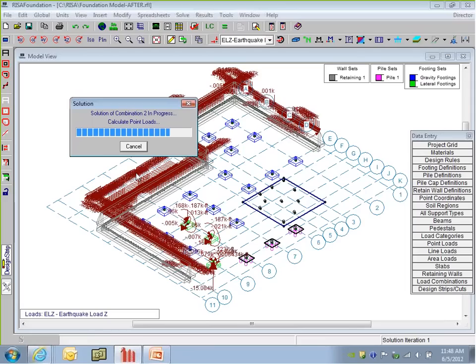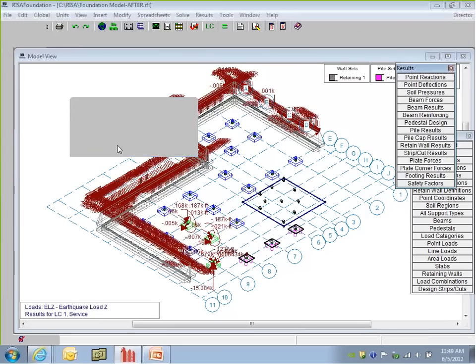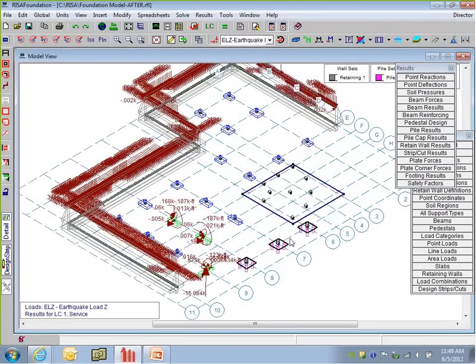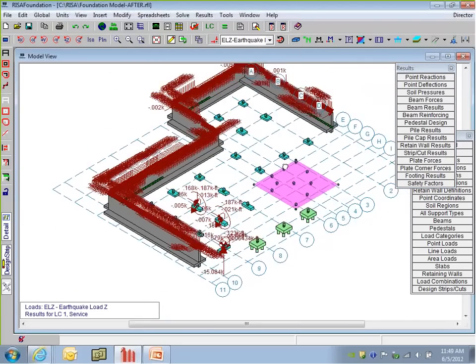And in concrete design, you really always need to do an envelope solution. You take each single combination, you put it all together, and you get your envelope solution, and concrete and reinforcement are designed based on that. So you really don't get a choice, and we can see it's just going to run through these different combinations that I selected. Sometimes you can see you're breaking this into all the point loads. So in a larger model, it may take a second or two, but it runs through all those point loads that came in from RISA-3D. And we run the model and get all of our solutions. It also tells us here what it's doing at that point. So it's designing the footings, it's designing the pile caps, and we get information on that.